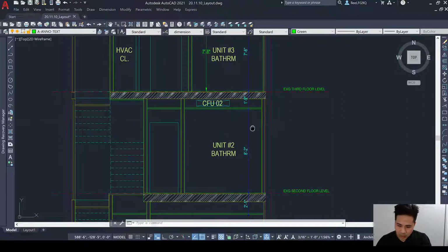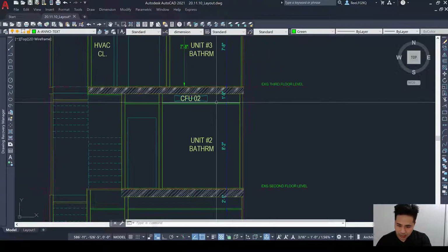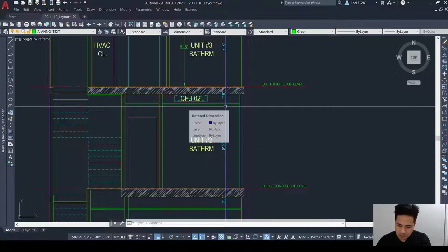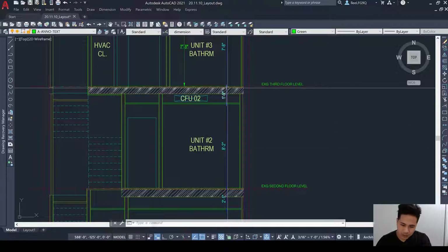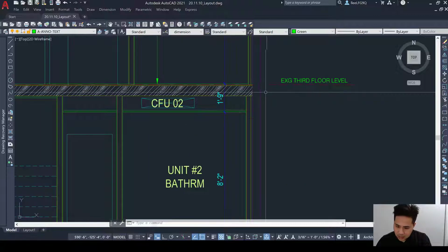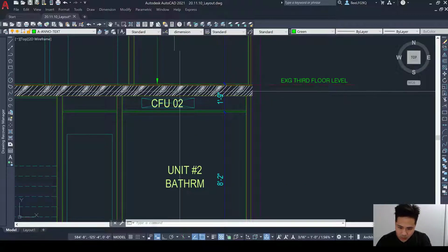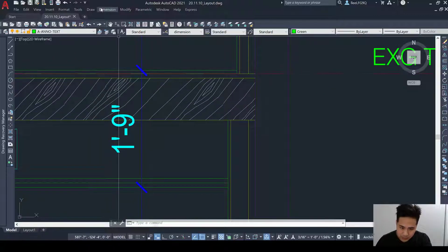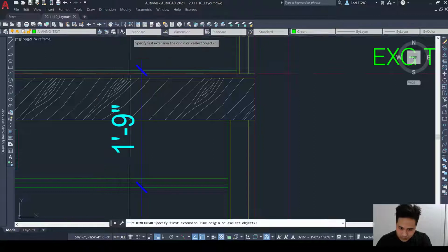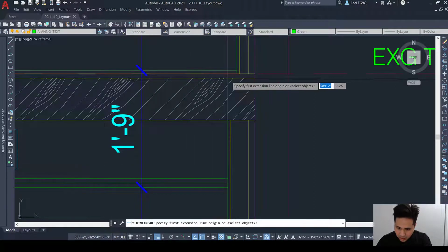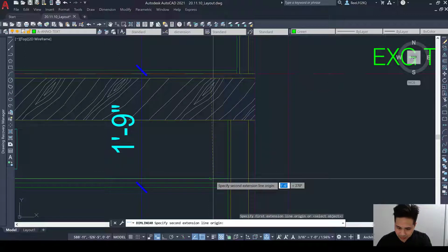Okay, in this floor we have a plenum, and a plenum is basically just the space above a drop ceiling and the floor above. Okay, or the slab above. In this case, this is a wood joist. Okay, so we're going to take it to the floor above. And that's approximately, I would say, like right here.